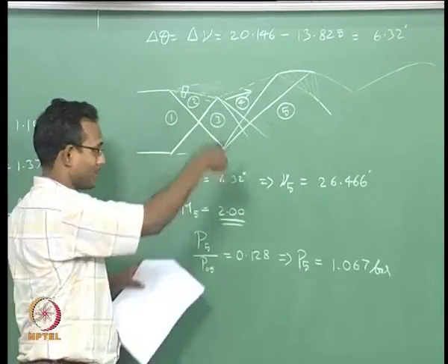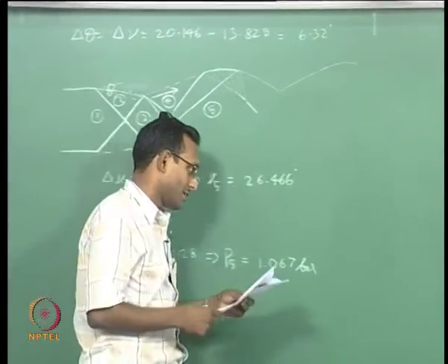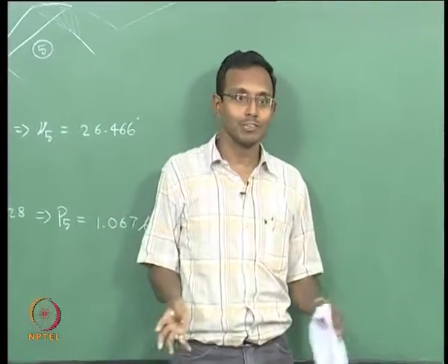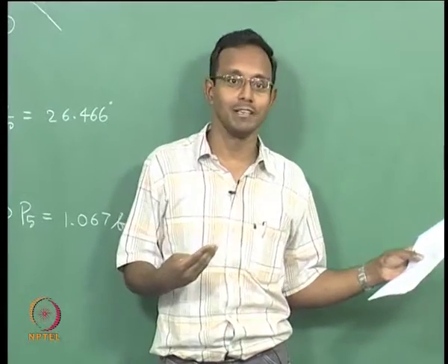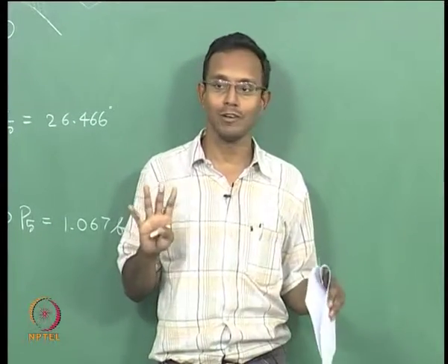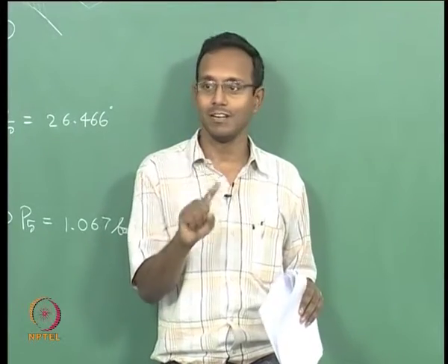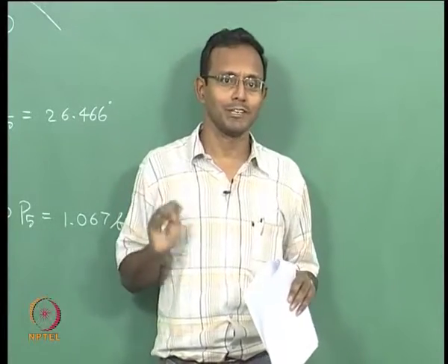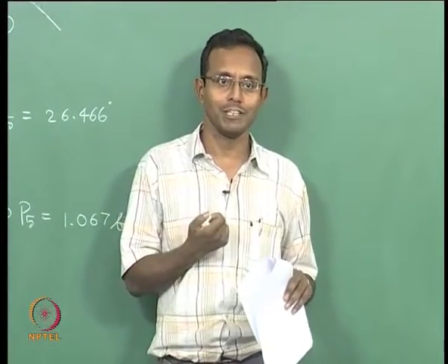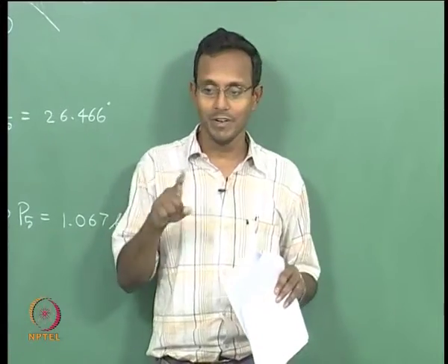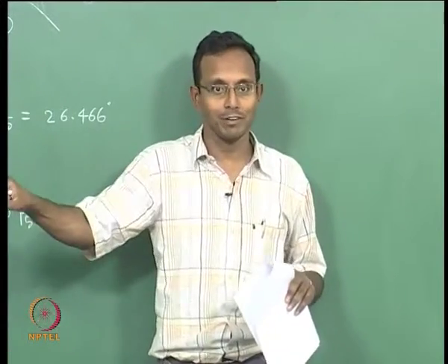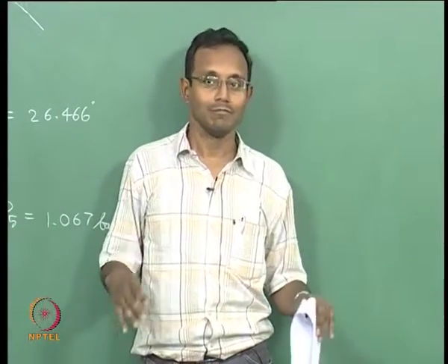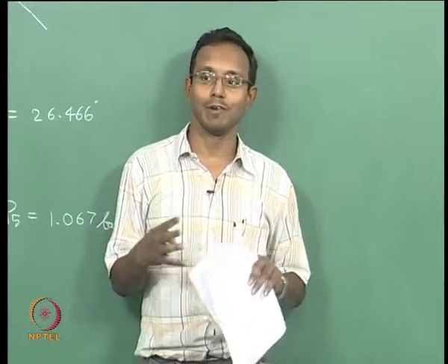I do not want to disturb this picture anymore, we will go to a separate picture. This has nothing to do with compressibility anymore, it is just fluid mechanics. Viscosity does not care so much about compressibility. Viscosity is just something that worries about high concentration of vorticity somewhere and low concentration of vorticity some other place. That is not liked by viscosity. One place has very high vorticity concentration, another place has no vorticity. Immediately vorticity will be taken from one point and given to the other. It wants to make vorticity equal everywhere,